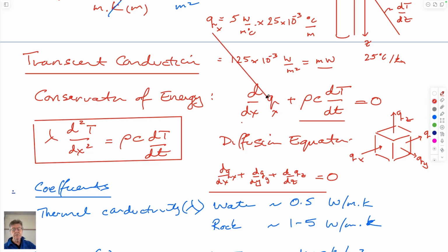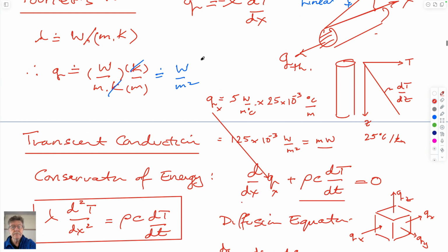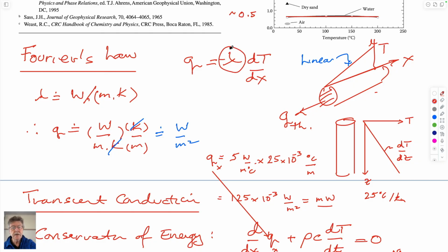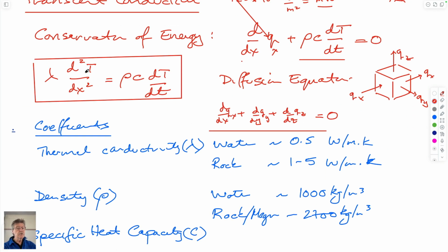So if you substitute Fourier's law into here and rearrange it, you end up with the diffusion equation. And this just says that the thermal conductivity, which has come from this relation here, times the second order derivative of temperature with space, with x, y, and z, has to equal the amount of heat that accumulates. And so if there's no heat accumulating, this term would be 0, and in 3 dimensions, this equation here would be replaced by, this would just be a second order PDE.